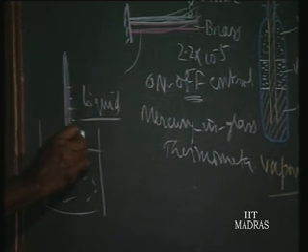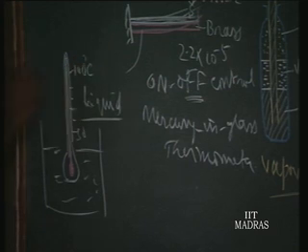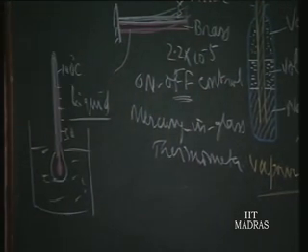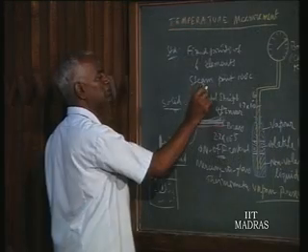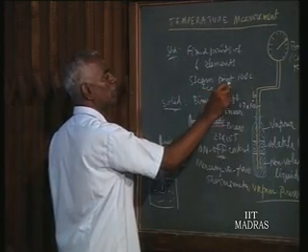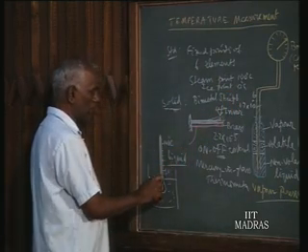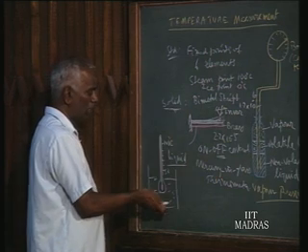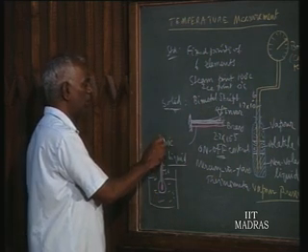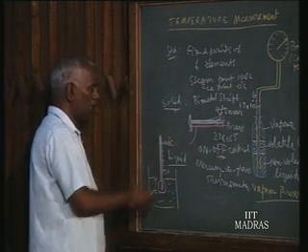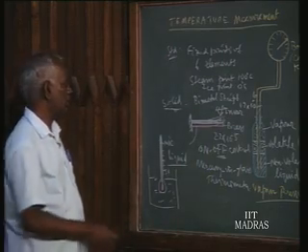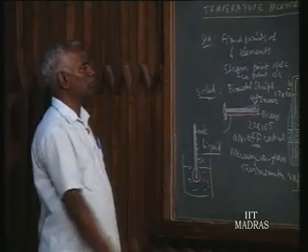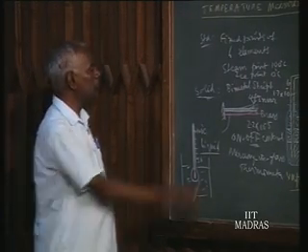terms of, say, 30 degrees. This may be 100 degrees centigrade. So it is being calibrated. This calibration is done by using one or two of the fixed points. So the ice point is 0 degrees centigrade. Once you put it in ice, mark wherever it stands as 0, and boil water and place it there, and where it stops, you call it 100 degrees, and divide equally the gap between 0 and 100 into equal parts. That's how the thermometers are being calibrated by using the fixed points.